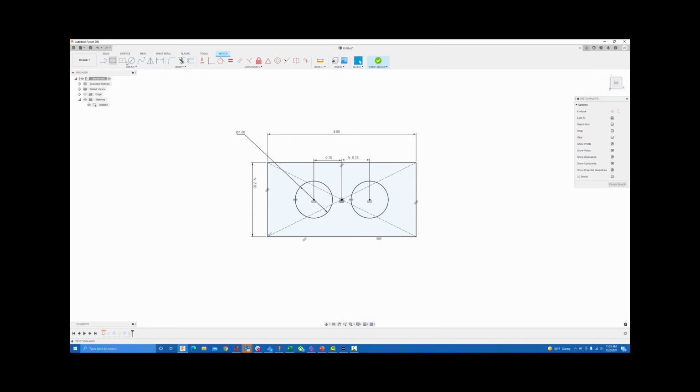Now another cool thing is I could come in here and say, in reality, maybe I want to add some fillets here, and sometimes I'll add fillets as a feature, and sometimes I'll add them as a sketch. Here I'm going to add them as a sketch because I really want it to work on both the front and the back and have them all tied together. Whoops. I'm going to undo that because I like to do these all together so that you'll notice that it ties all the parameters together. So it's basically one parametric value will control all of those.